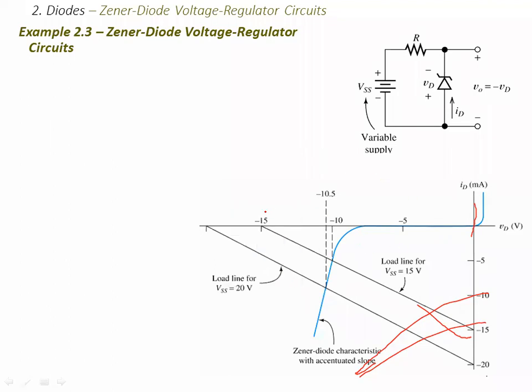So what are we saying? We are saying there's a certain voltage which if we reach, right? So in this case, it is 10, which is our Vz, and here it's minus 10.5, right? And then given a circuit with a value of R and a value of Vd, you can determine the maximum and the minimum current that can flow. The only thing that you have to take note of is that the currents are in the negative direction relative to what we use here because we are reverse biasing the diode.